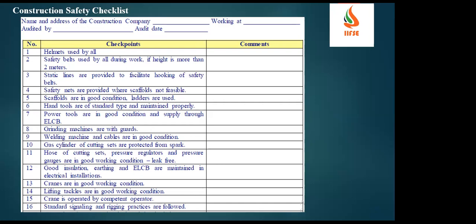Whatever scaffolds we are using, we have seen in the engineering 1 syllabus. There we have seen scaffolds. The scaffolds must be verified and certified by the authorized person. Only then must those scaffolds be allowed for performing the activity. There we check soil condition, base plate, sole plate, cross bracings, then access. We check the mid rail, top rail, then the condition of the bracings. The pipe should not be bent, should not be rusted, and should not have any weld repairs. The clamps must be done properly, and it has to be tied up with any fixed structure